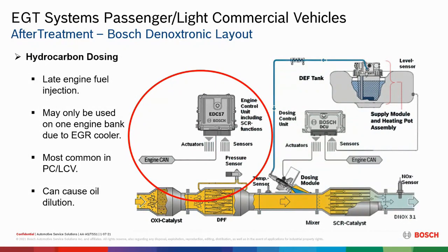So the vehicle has other issues, and it's doing a lot of regenerations, more than normal, because of other problems. Now what's going to suffer is we're doing more dosing into the engine, and we're doing more oil dilution as well. So it's this catapulting effect of this whole thing going down, causing more problems to happen as one item goes bad. So again, if something fails in this whole aftertreatment system, you must take time and look at the engine control system to see if there's any problems with that at all. Really, it's a key factor in that.